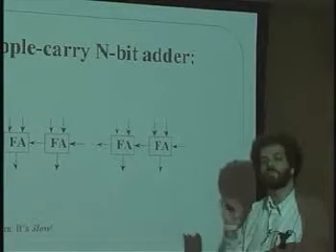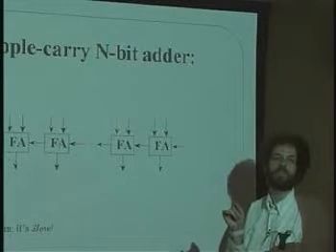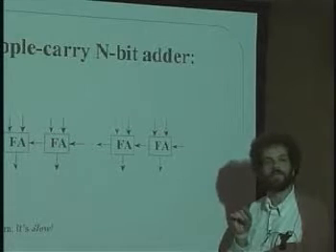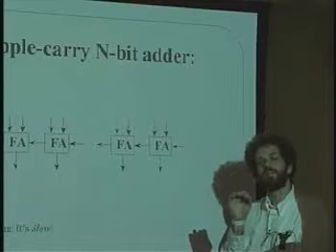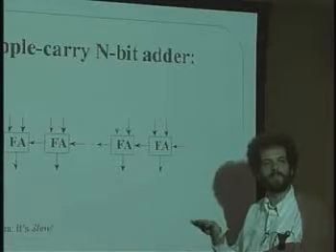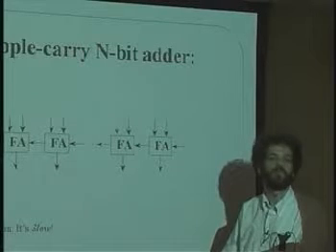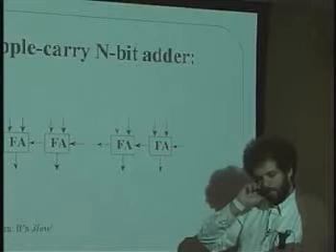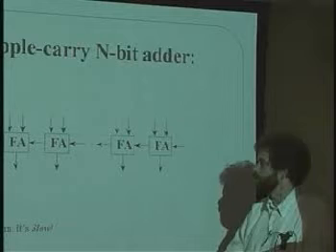Okay, and in general, the rule with a simple adder like this is if the carry out agrees with the sign bit, then no overflow has happened. So in the case of a positive number, the sign bit is 0, and you expect the carry out to be 0 also. However, if the sign bit is 1, meaning the number is negative, and you add two numbers together, and you do not get a carry out of 1, then something's wrong. It means you've overflowed going negative. Okay. So anyway, that's a general issue that we're going to have to figure out how to deal with: overflow in these summations in the ALU.